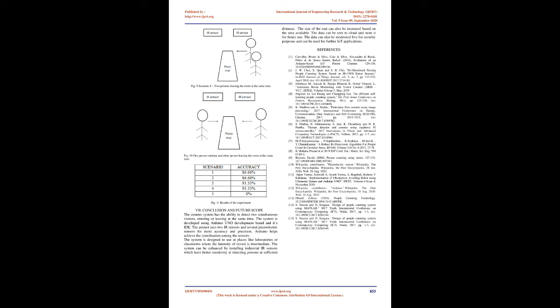The person then passes by the IR sensor, which detects the entry. The algorithm is designed in such a way that if both the piezoelectric and the entry IR sensor are high at the same time, it detects the person and the count is increased by 1. Hardware of the project, which includes IR sensors and piezoelectric mat.